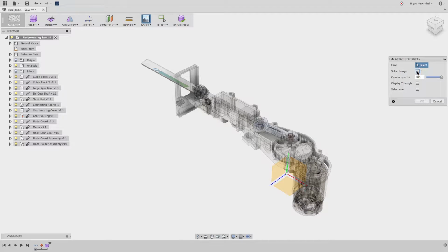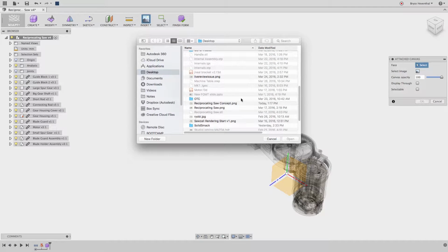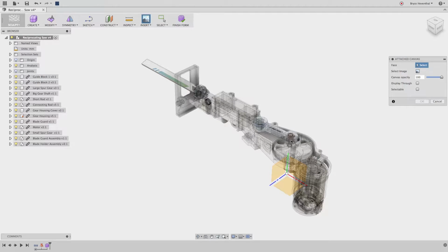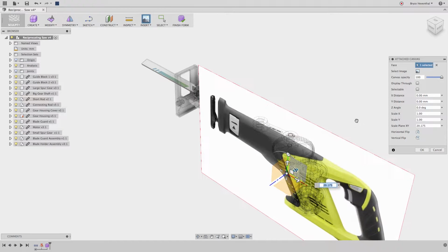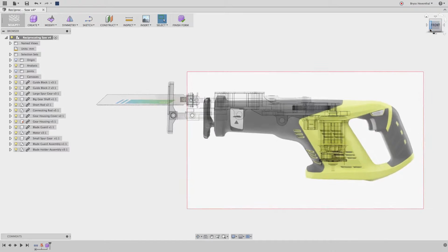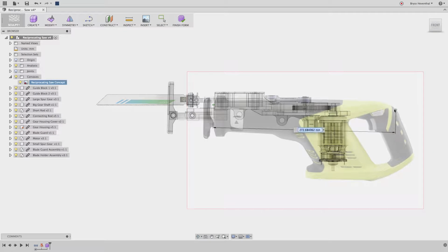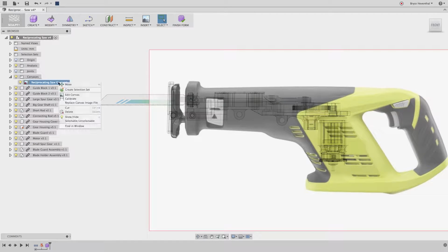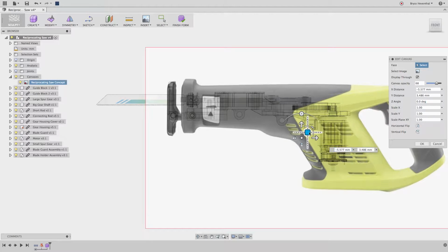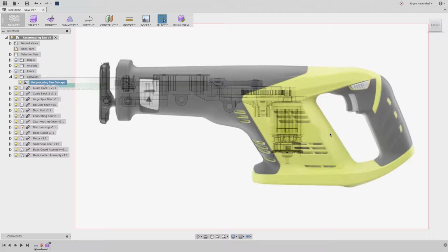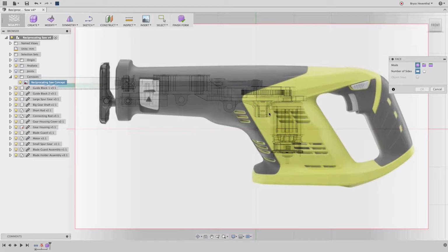One of our industrial designers created a concept sketch in Sketchbook for us to use as a starting point for modeling our plastic housing around. We can resize this image to the appropriate size, but this PNG file used for the image does not have units. I can calibrate this image using a known measurement to better approximate the size of this image. Once the image is in place, we can start creating a T-spline body. We will use a face to start our design.